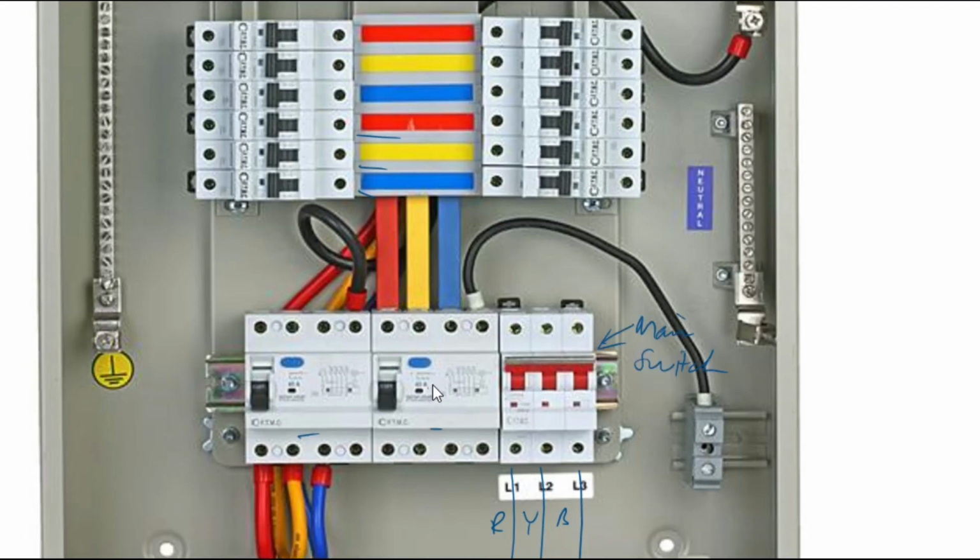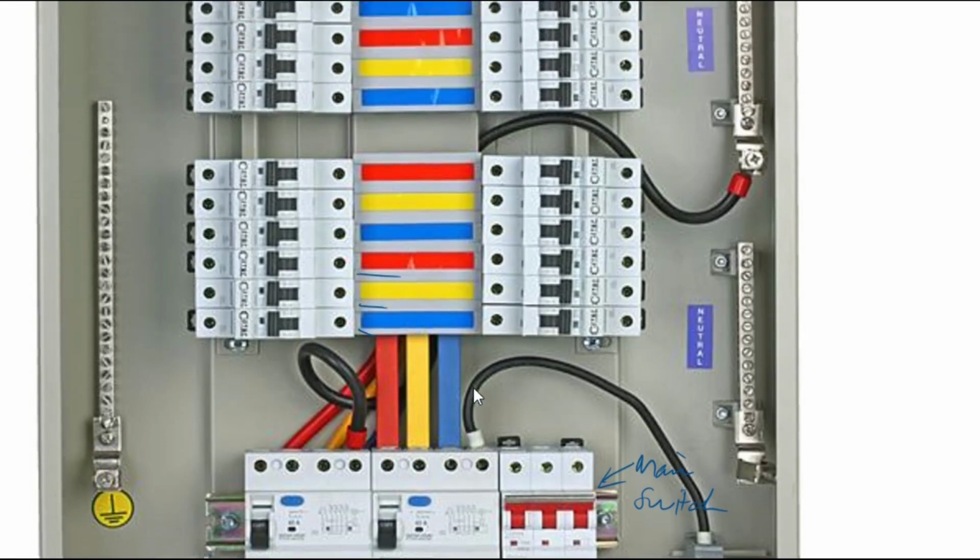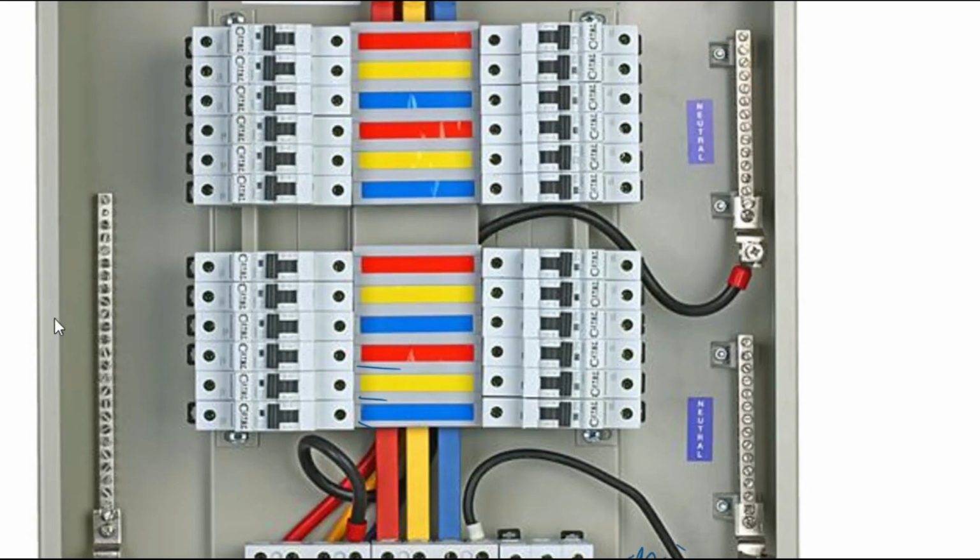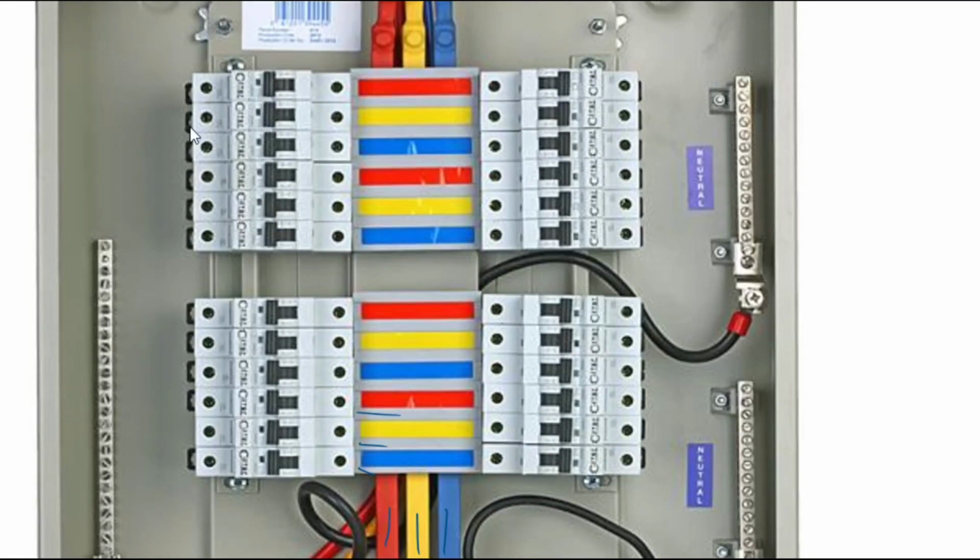Once you have your supply connected, you will then have a series of connection points. Here you note three thick copper bars that are connected to various takeoff points. These three copper bars, each with one phase, red, yellow, and blue, are connected to various points along this. This is called a bus bar. The reason for that is you will have this set of bus bars for each of the phases, the red phase, the yellow phase, and the blue phase.